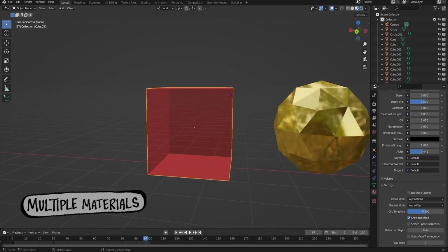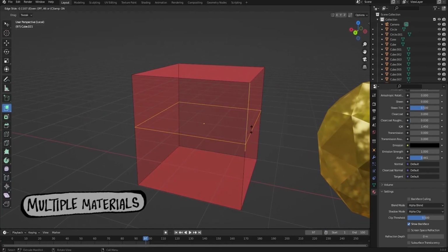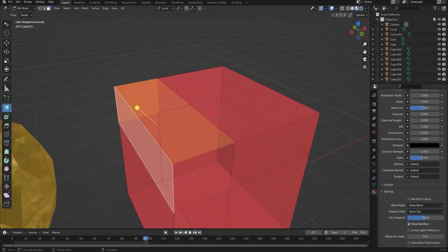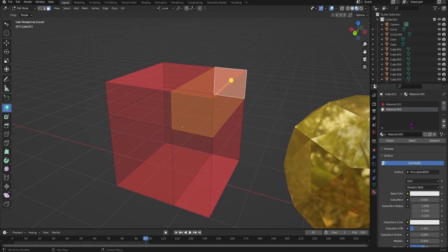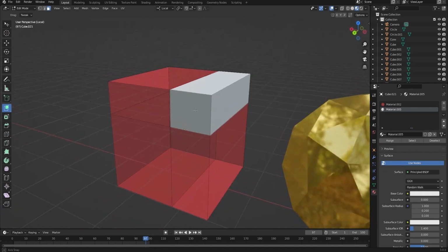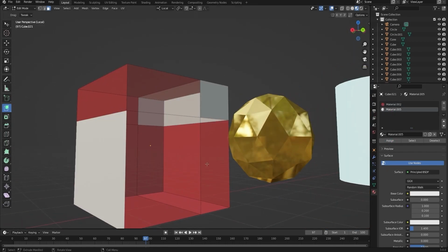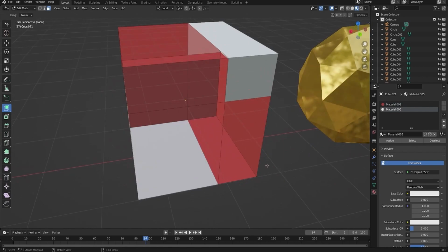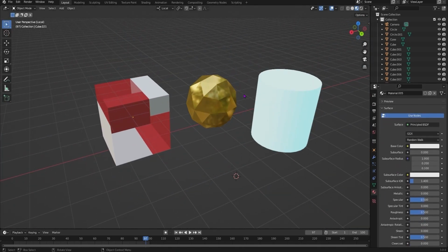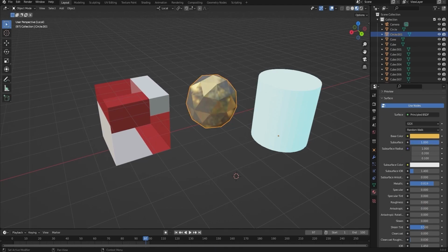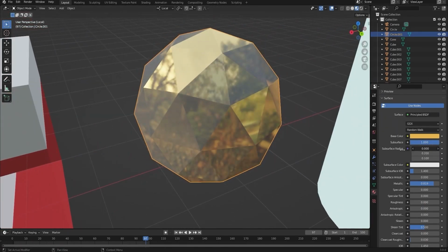There's a way as well to add multiple materials onto the same mesh, and how this works is you create multiple materials in the right hand tab and then you can select the faces that you want to be the material that you have selected, and then you hit the Assign tab so that those faces will now have the new texture. And by the way, when you change any of the properties of your material, it will change it on your objects as well. And it'll change it for any objects that have the material that you're trying to edit.